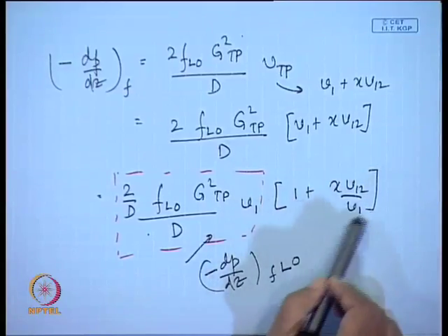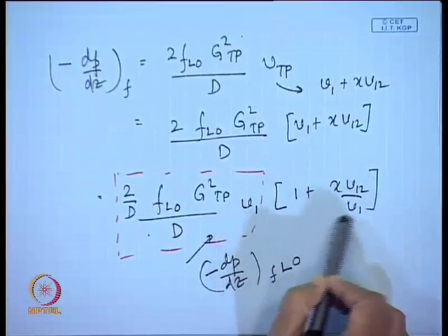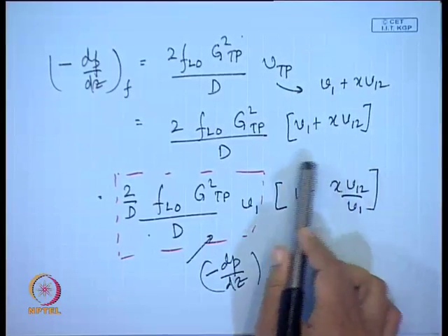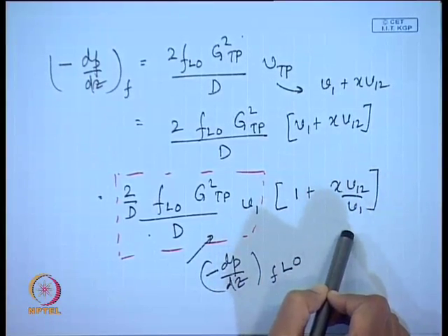When only liquid is flowing through the pipe, you need not even measure the pressure drop, you can just find it out from standard single phase flow equations. So, once you can find out the pressure drop for only liquid flowing or the entire mixture flowing as liquid through the pipe, then along with that a correction factor has to be incorporated. The second term, this particular term, is the correction factor, which is again expressed in terms of your known physical properties.